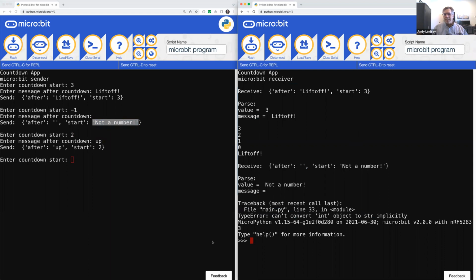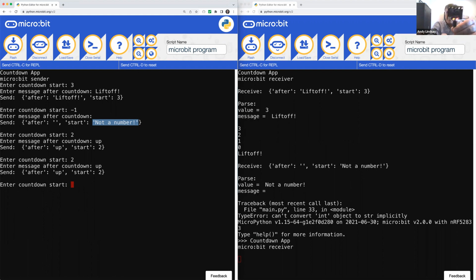It's not responding. It just finished displaying its exception message. So I'll try it again, but nothing's happening over to the right side. And nothing will happen until either you load the new program on, or, remember, there's a reset button right there, right next to the USB port. So you can press and release that reset button.